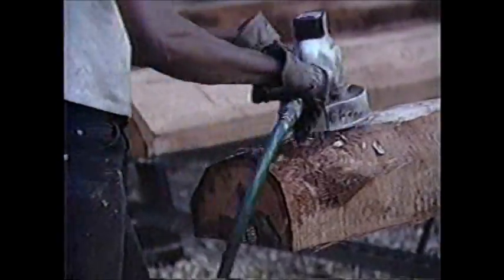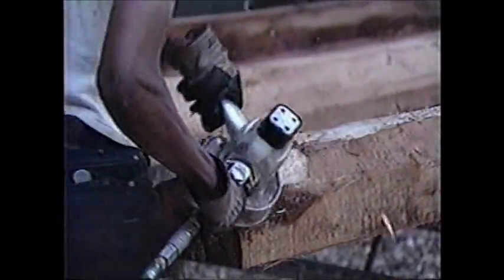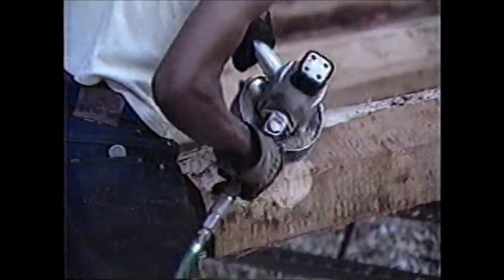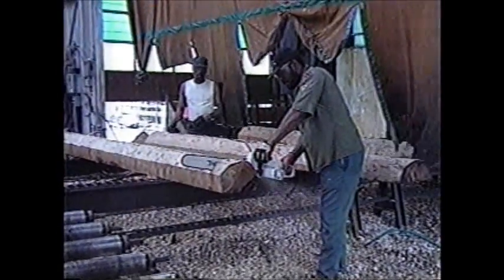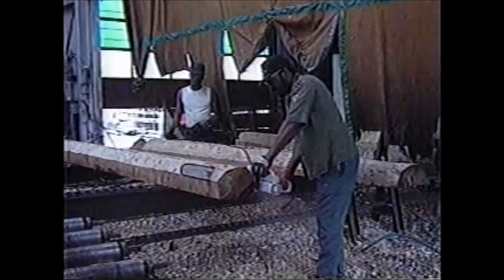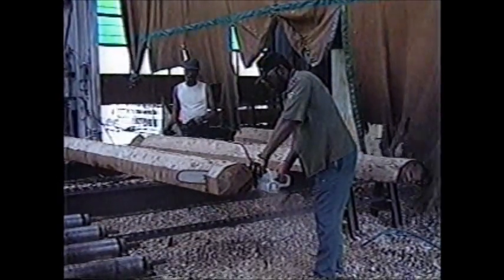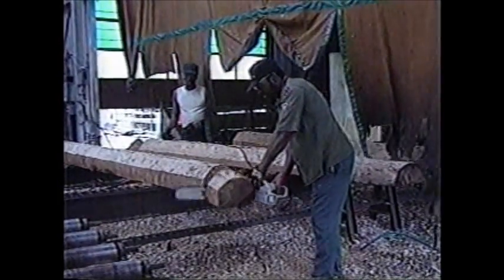The soaking process softens the wood fibers and produces superior veneer. By minimizing checks and splitting, the usefulness and value of the veneer is maximized. The flitches entering the plant have all remaining bark removed and are end trimmed to a specific length. They are then conveyed to either the vertical slicer or the stay log lathe.